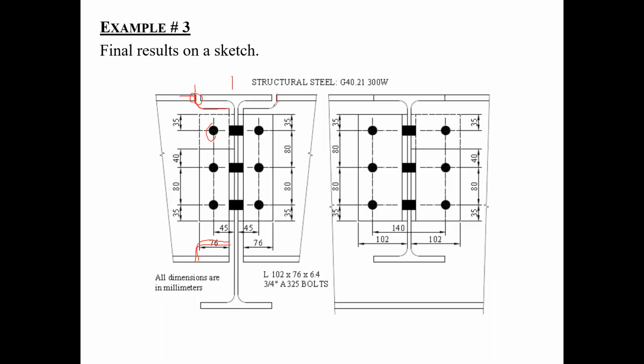So you can cope a beam at the bottom, you can cope a beam at the top. That's number one. Number two, when I'm putting these beams together, you have to remember, I only have one crane, and the crane basically picks up one piece at a time. So if I decide to connect, like in plan view, here's my girder, here's my beam, here's my girder, and here's my beam. In plan view, if I decide to erect this beam first, when I come and put the connection here, I'm going to have to put something to hold it there temporarily. So normally I will put one bolt in this connection here, one bolt in this connection here, and leave it there so it holds the beam temporarily, so that when I come and put this beam beside it and start putting the bolts across, the bolt head that I put here will not interfere with this angle here.